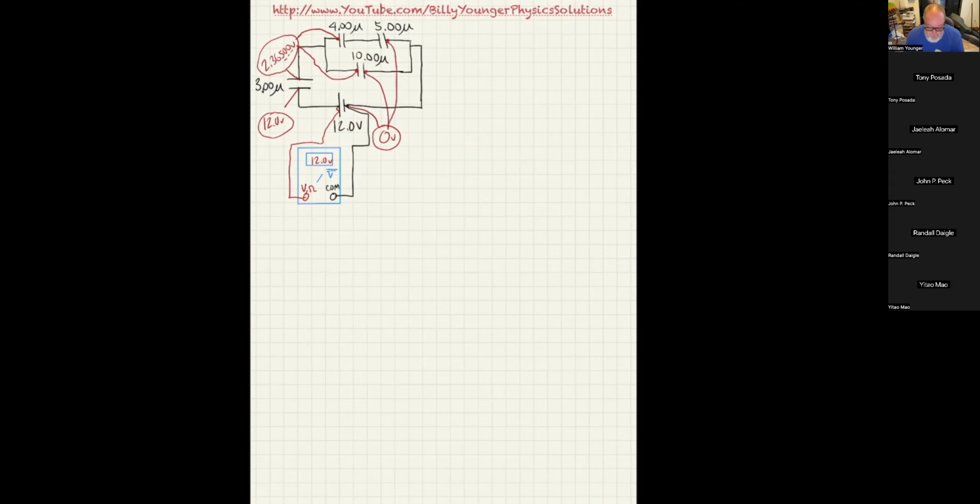So you can tell clearly the total voltage difference across the 4 and the 5 microfarad capacitors is 2.365, but we already know what the voltage across the 10 microfarad capacitor is. So I'm going to continue with my solution and say that V10 is equal to 2.36500 volts. So that's another answer.